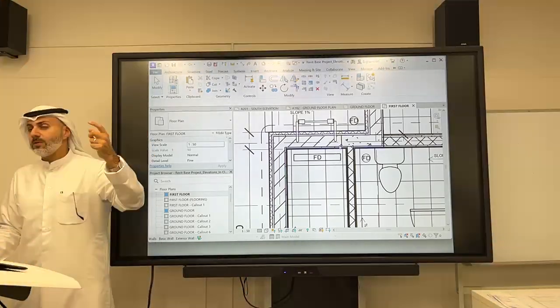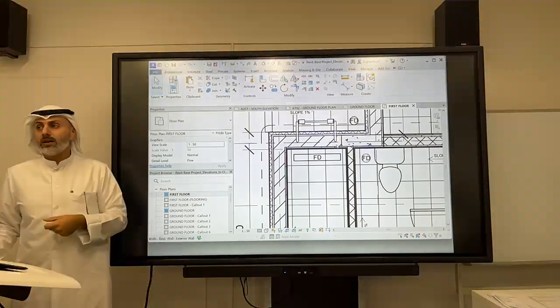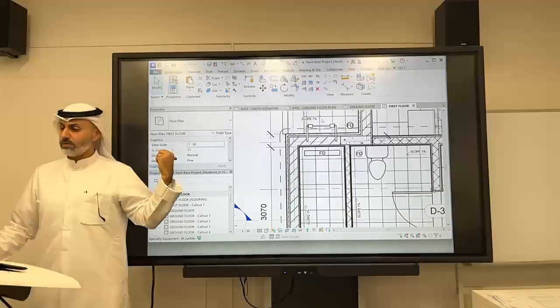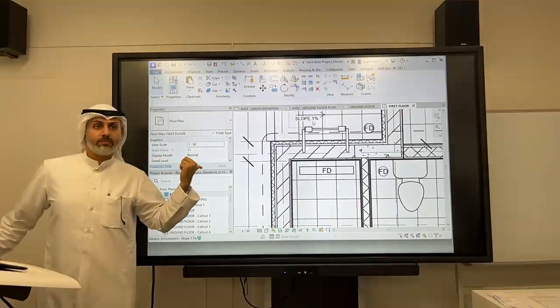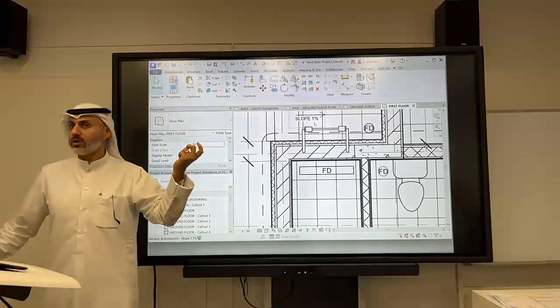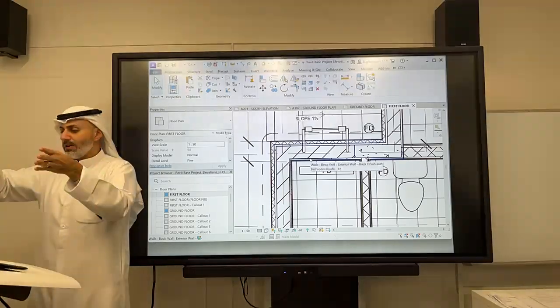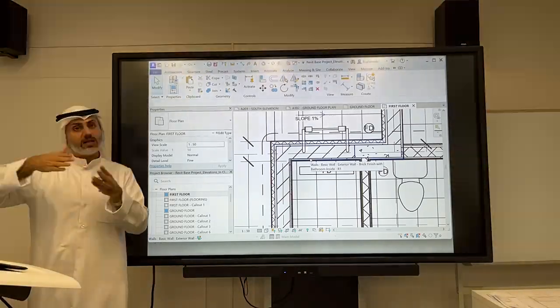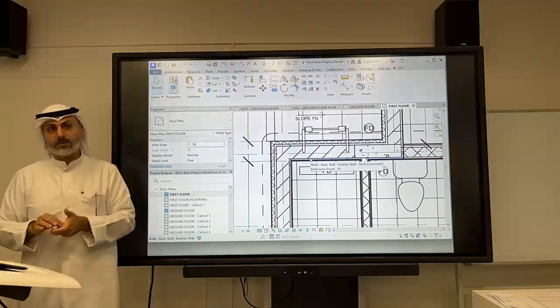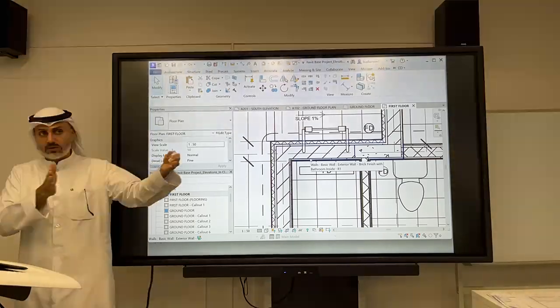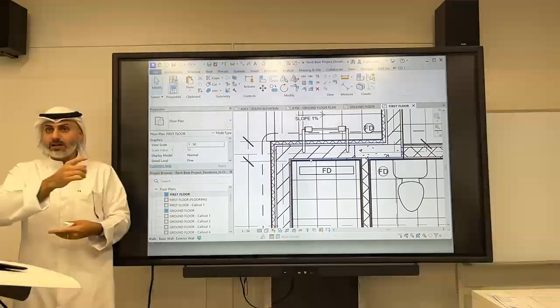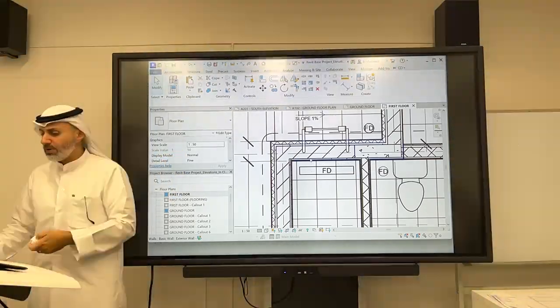Or if the column, let's say, has to be 30, then you can change the core. The core becomes 30, if the structure has no other solution. We can change the core to 30 so it goes with the column. It might cost more, you might lose width of the room, but design wise and finishing wise it will be better.